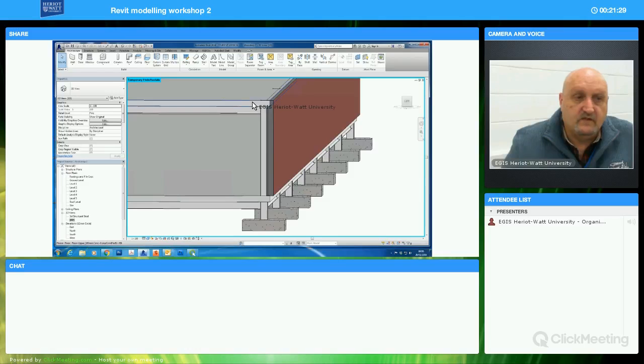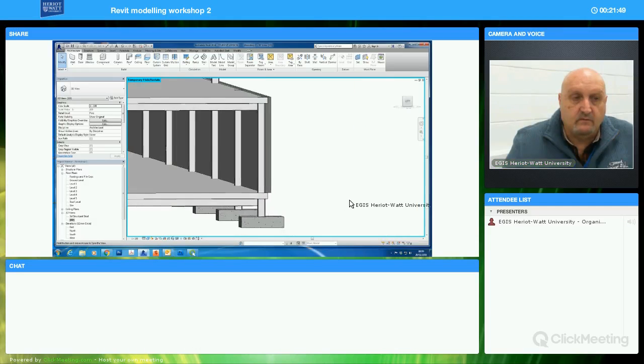This first level floor was just a copy of this, but now we have to rectify that and extend the boundary of the ground floor so that it fully supports the wall, but the floor above it is only going as far as basically reaching the cavity. It's supported on the inner skin, the inner leaf of the wall.